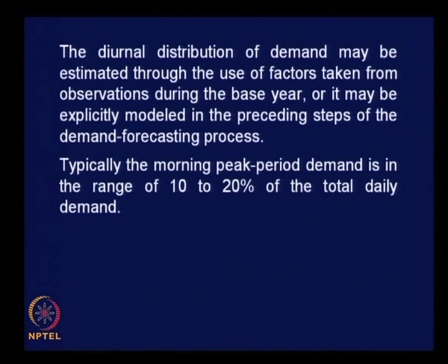Typically the morning peak period demand is in the range of 10 to 20% of the total daily demand. The range itself is very wide, 10 to 20% of the total demand is occurring in the morning peak, which might be spread over normally 2 to 2.5 hours, maximum 3 hours.